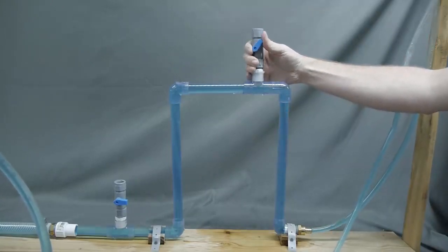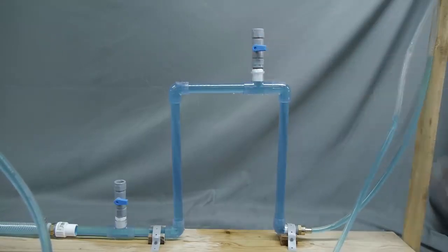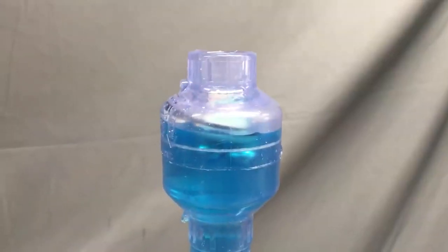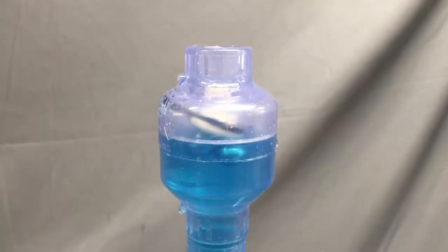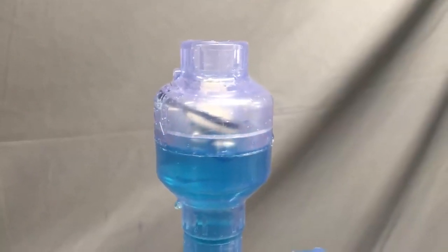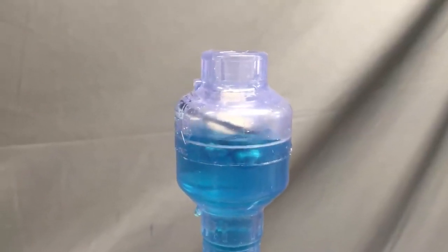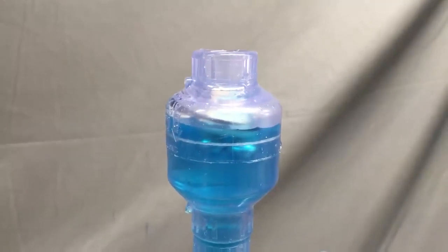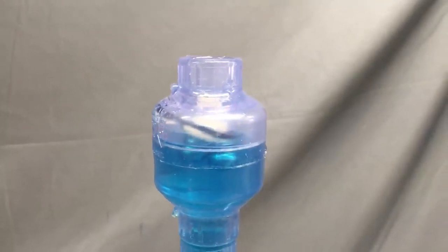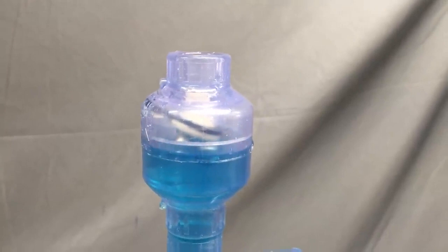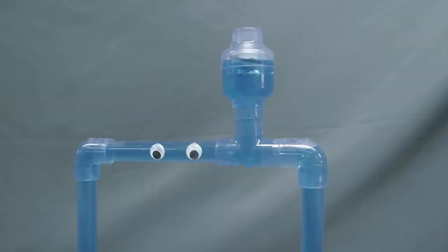Cities don't want to send out technicians to bleed the air out of pipelines every day, so many pipelines are equipped with automatic air release valves. These are a simple but clever solution for releasing air from the high points without any human intervention. I built an example of this by gluing a float to a check valve. When there's no air in the pipe, the float holds the valve closed. But when a big enough air bubble grows in the pipe, the float acts like a weight and pulls the valve open, venting the air from the pipe.